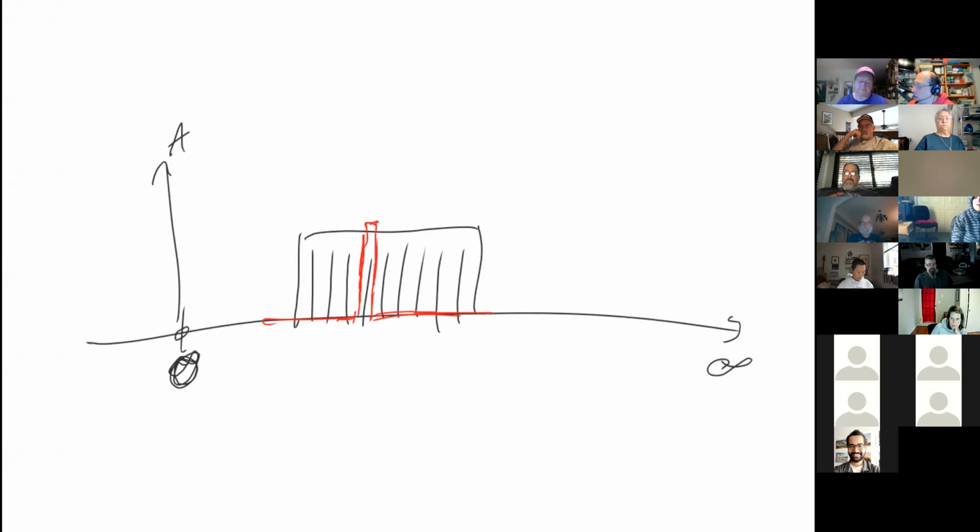If we're listening to Morse code, this would be like a 500 hertz filter. If these signals are actually single sideband signals, we could put a filter here that would be this wide. And we would reduce our cacophony from like 8 signals down to like 3. Which isn't enough, but we're doing the best we can. So that's a way to improve the selectivity of your receiver, add filtering.